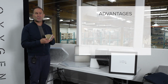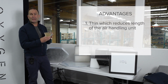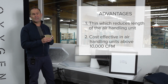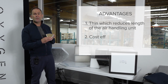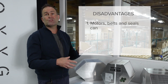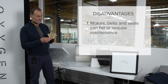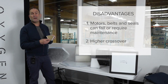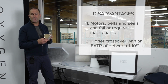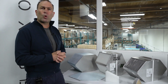The two main advantages: one, you'll see that they're quite thin, so it reduces the length of the air handling unit, and secondly, they are quite cost effective in large air handling units above 10,000 CFM. The two main downsides for wheels are, one, you have motors, belts and seals that can require maintenance or could fail. The second is wheels will typically have higher crossover and have an EATR of somewhere between 1 and 10%. The second technology that we're going to talk about are cores.